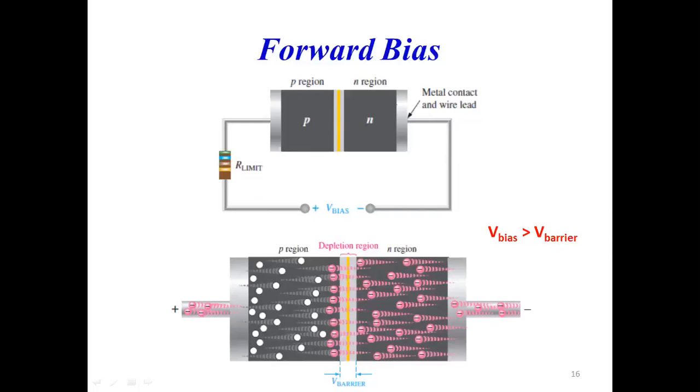See, basically, students, there is a movement of electrons. The electron will recombine with the hole, and they will move from one hole to another hole, from this hole to the next hole, and it will appear that the holes are moving, but actually the conventional current direction is opposite to the direction shown by the flow of electrons. Now, this flow is possible whenever you are applying a bias voltage which is greater than the barrier potential which is present here at the junction.